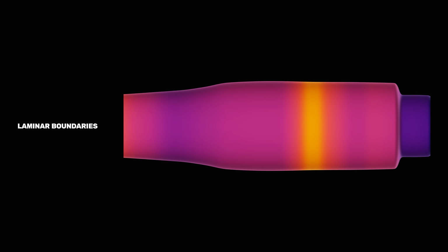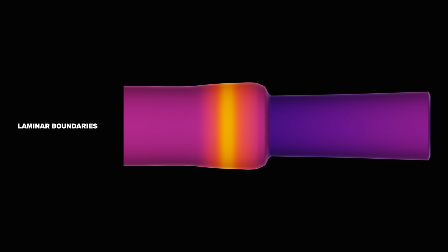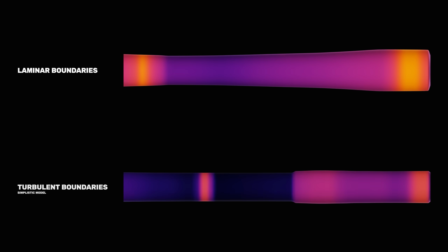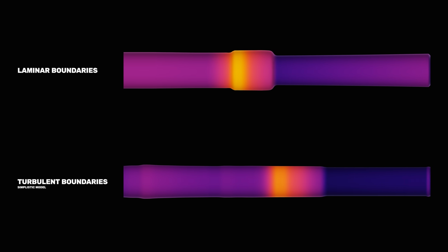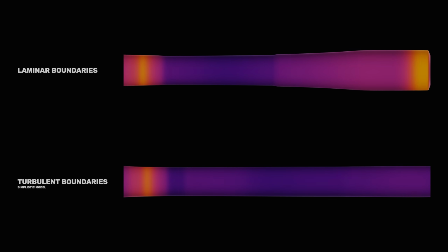The next issue to address is turbulence, or the lack thereof. Turbulent flows form at the valve, within the pipe itself, and at the outlet, and I believe this is partially responsible for the characteristic fuzzy pulsing sound that engines generate. Turbulence is extremely complicated and impossible to fully simulate in one dimension, but I implemented a simple model anyway. It needs a bit of tweaking, and it is pretty subtle, but I think it's fine for now.